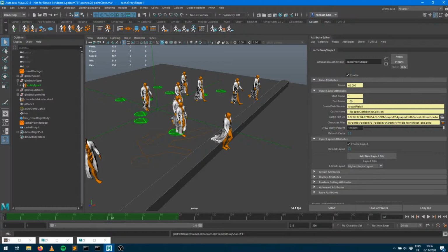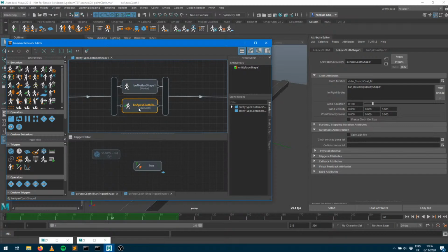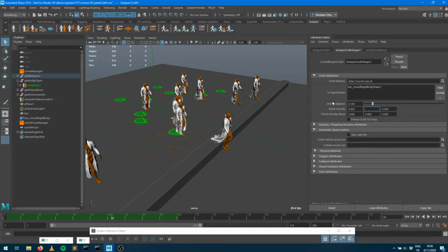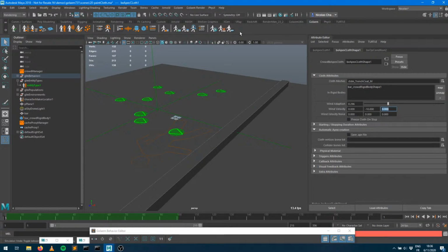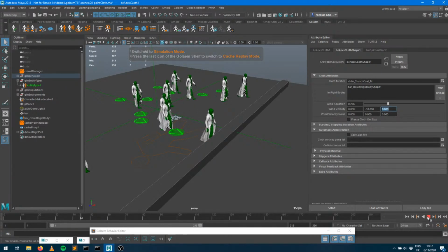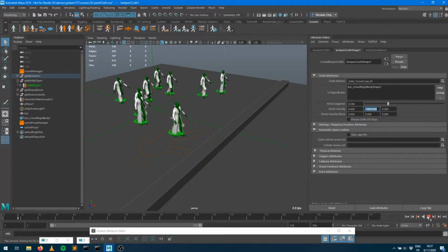How would one go about adding external forces to Apex cloth, like wind or turbulence? Turbulence is not really easy to do with the current setup, I would say. But the wind is actually something which is part of the Apex cloth behavior. You've got something called the wind velocity and the wind noise. So let's say we want to produce some wind in the minus x-axis. I'm not sure what the orientation is, we'll probably have to check the documentation here. But if you produce some noise, some wind, well, it's probably not high enough, right? Let's change the order of magnitude of this.